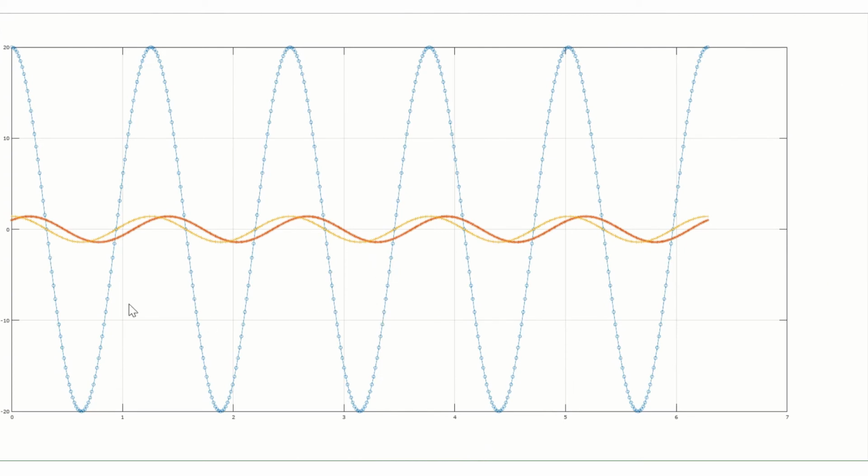So here you see that this is the one in slightly on the lighter end of orange, I would say. So here you have another line, and you see that the amplitude is correct. Here, basically you're comparing the I new which you have just calculated and the I which you obtained by using the equation V divided by Z, and you see the amplitude is the same, but now the difference is the phase shift. So again, we have to define what is the phase shift in this case.